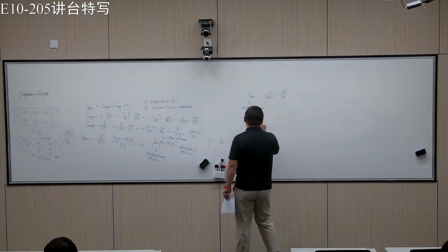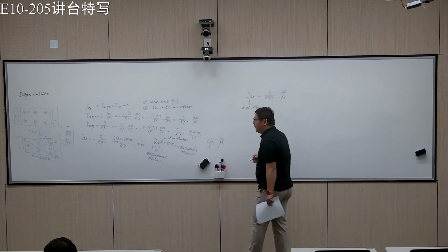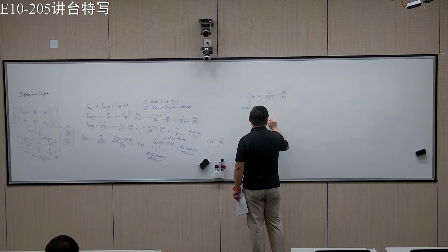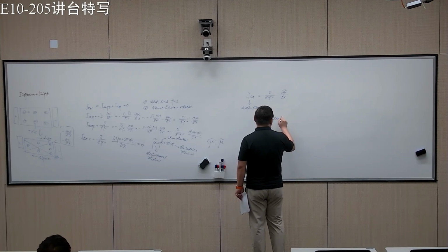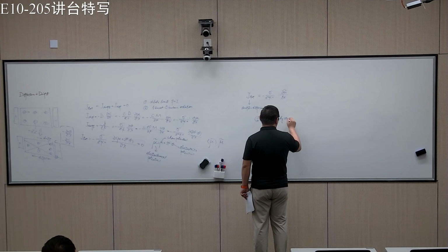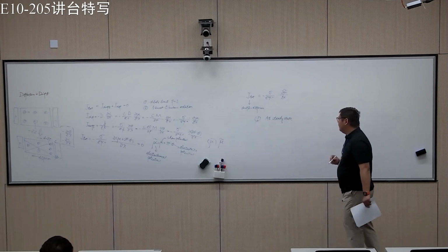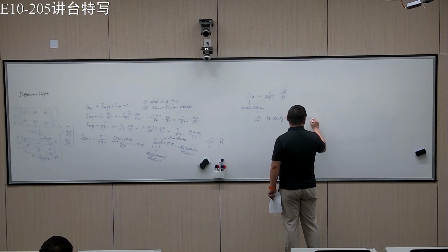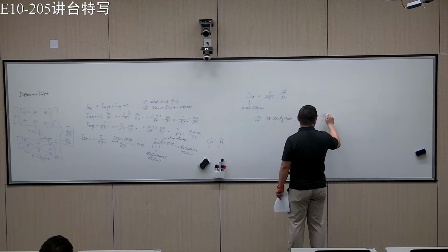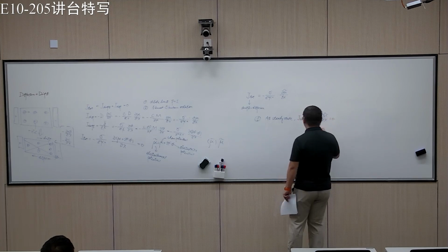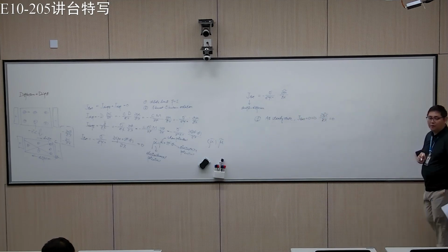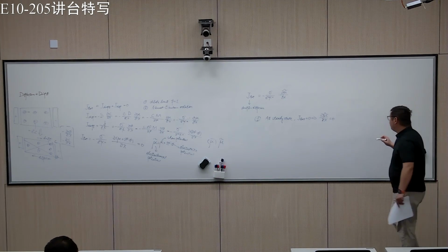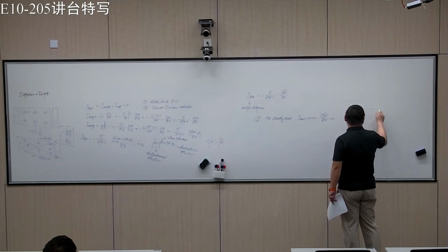The first thing is, if drift and diffusion cancel out at a steady state or equilibrium, then J total should be 0, which means the equilibrium condition is the gradient of electrochemical potential is 0.